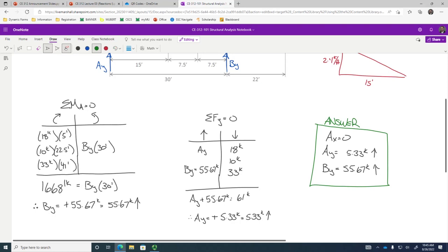They are pretty straightforward. One thing I will tell you, I think it's either this assignment or the next one, but one of them has a beam with some variable change in geometry, like the beam gets deeper or shallower along the span. That doesn't matter for the purposes of computing reactions. It will affect things like computing deflections, but not reactions. As long as your structure is statically determinate, the beam could be steel, concrete, popsicle sticks, it wouldn't matter, and you get the same reaction.